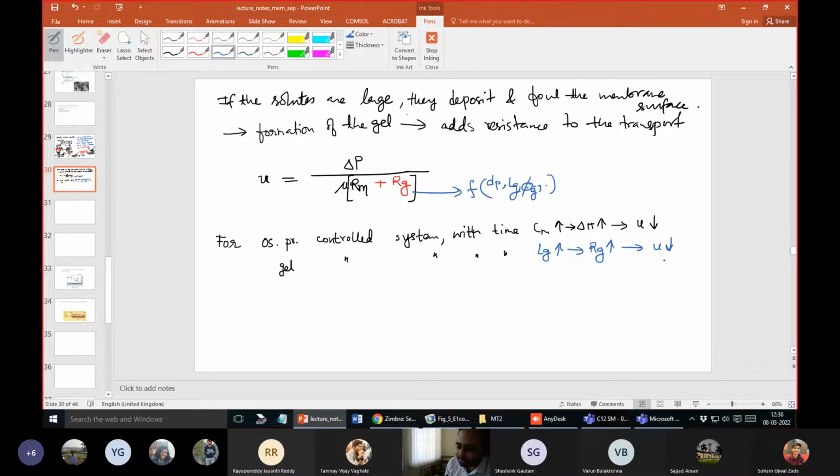That is the problem, right? The increase in the concentration of the solutes that are getting separated over the membrane surface creates a whole lot of problems. And it is true for all types of filtration involving membranes, except for gas separation, where things are a little bit different. But for all other types of liquid filtration process, it would come within this zone, right?